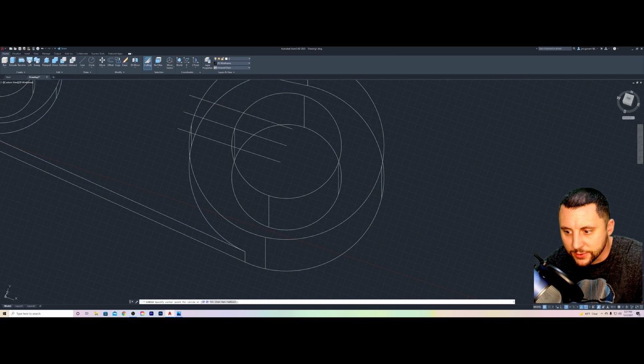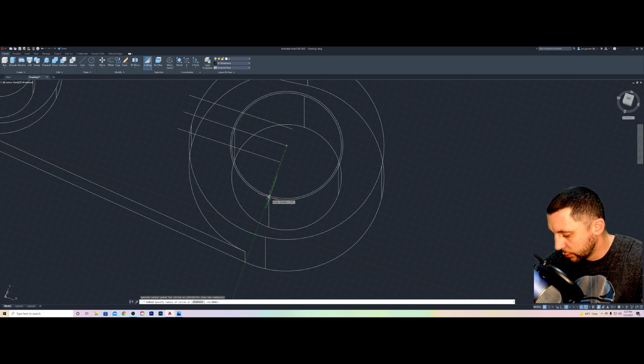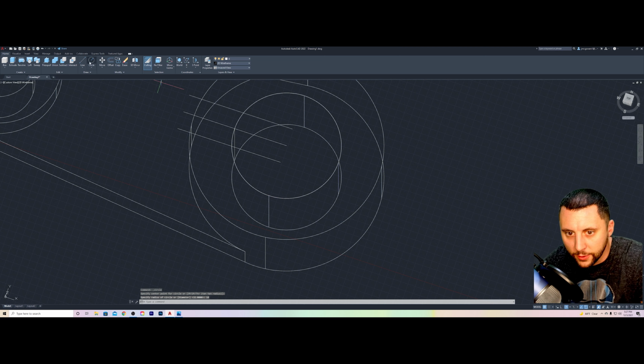You need that same circle size, which is going to be here to about there, but you also are not going to get a snap on that 3D model. So we're going to do a radius of 18 or diameter of 36, whatever you want. And then that's going to allow me to get this intersection here and draw to there.